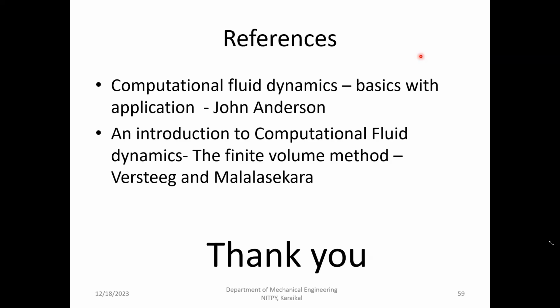So now how to minimize it? Mitigation and minimization is going to depend on how we choose. First, we must make sure we are choosing our equations correctly. That is, if it is a laminar flow and you go with the k-epsilon model, the system will still give the answer. So you must check whether the flow is laminar or turbulent before choosing that model. And like that, you must look at that first. So that is the reason we'll always go for the validation part.